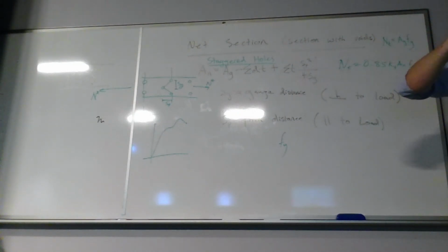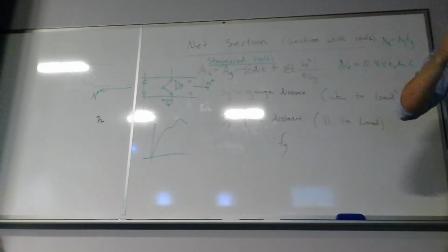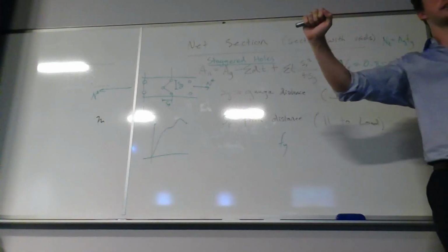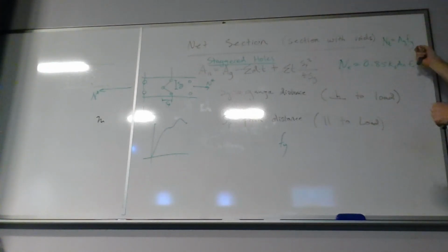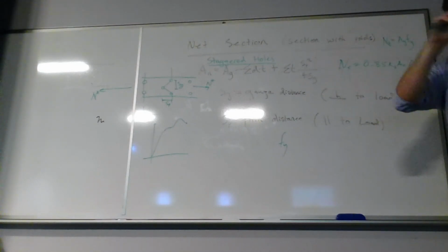Perfect, right? So what does ductile mean? It'll stretch. It'll stretch, perfect. So it'll start to yield. So before the point of failure is that stretching. It's that plastic deformation, right? So that's why we use Fy for yielding on gross section, because the moment it fails is when it's stretched and it won't go back. That's where we draw the line with failure.